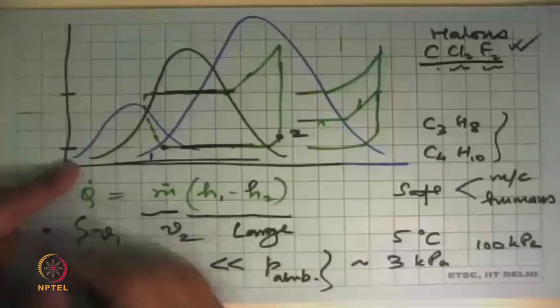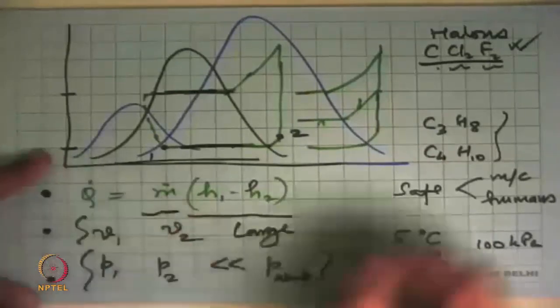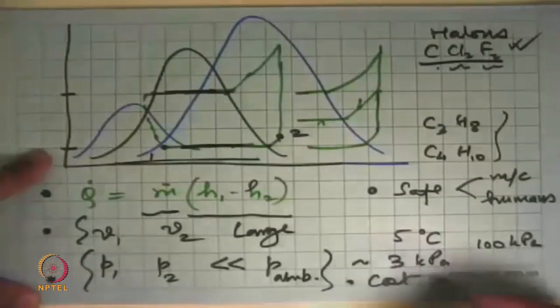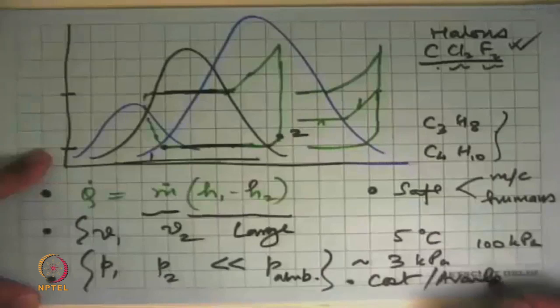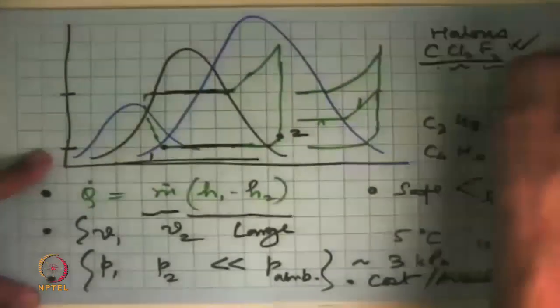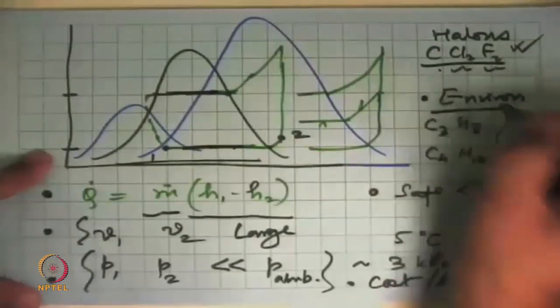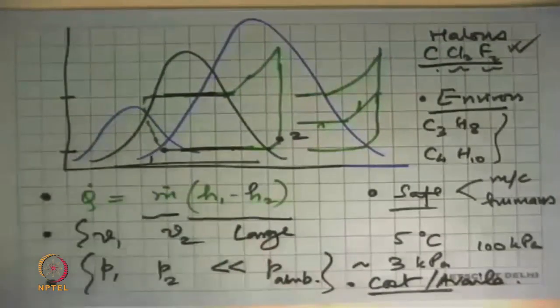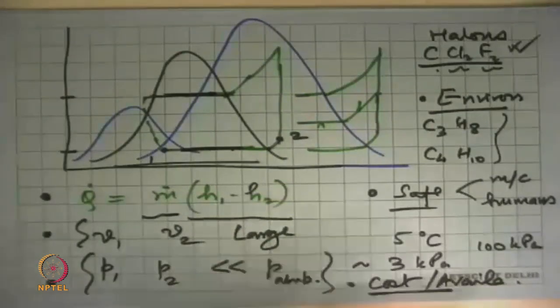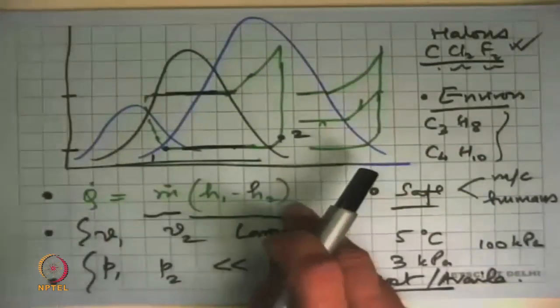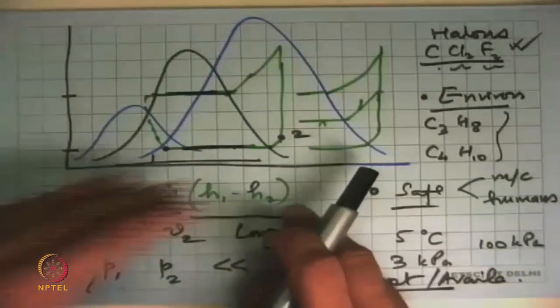Specific volume was another criterion. Then we look at heat transfer rate, safety, and then, of course, as an engineer, you always have to worry about cost and availability. And these days, environmental impact. So these are many issues that decide which substance to use in the refrigerant cycle. But the starting point is to ask: does the thermodynamics make sense? If the thermodynamics makes sense and the engineering is doable, then that becomes the candidate material for the next step of consideration.